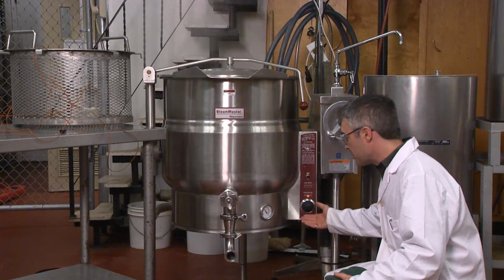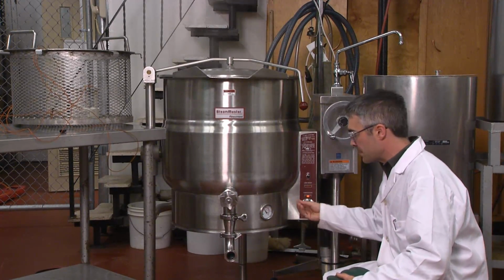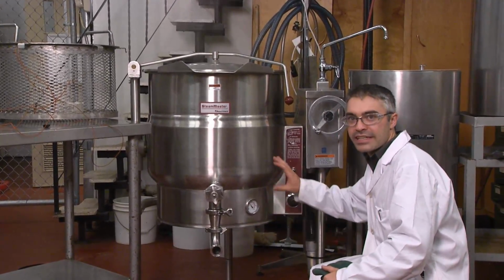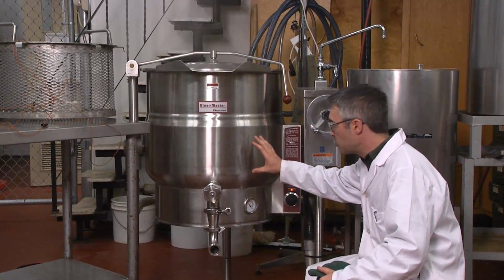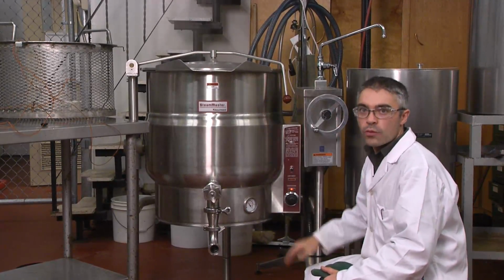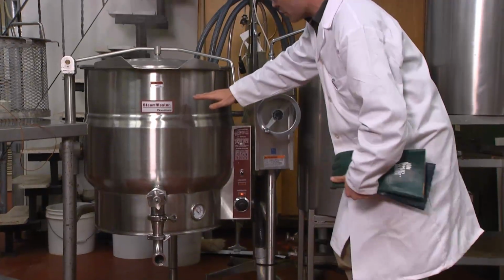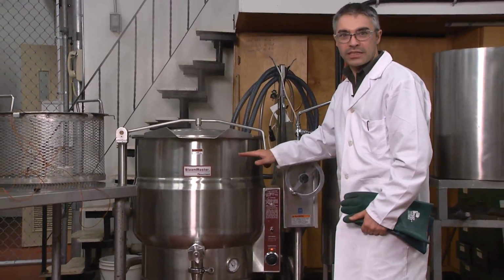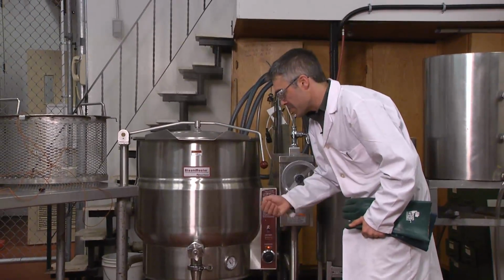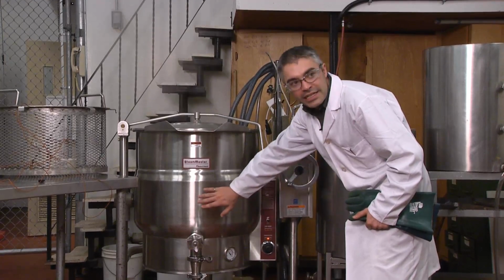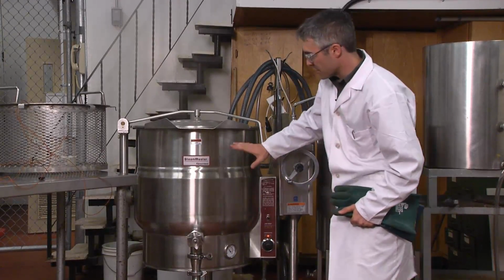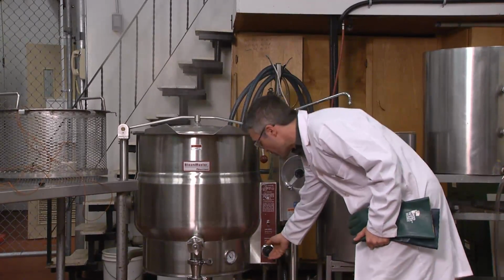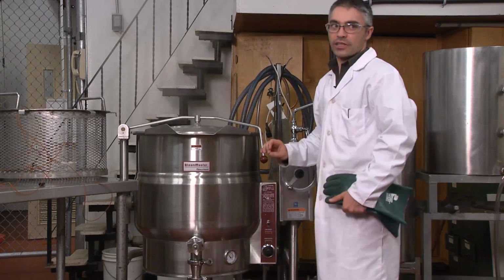It will not give you a specific temperature. It'll simply provide X amount of energy into the steam jacket, and you'll have to ascertain how much is sufficient to maintain whatever temperature that it is you're looking to maintain for a given load within the kettle. Our current load within the kettle is water, which we know at atmospheric pressure will boil at 100 degrees Celsius. We can slightly put a little bit too much energy into the jacket, which will maintain our temperature within our environment at 100 degrees for the duration of the experiment. We want to keep a rolling boil, but not excessively so.